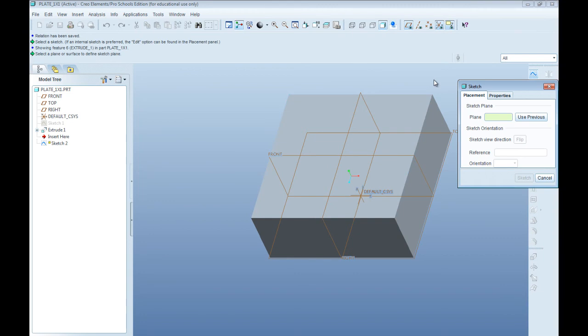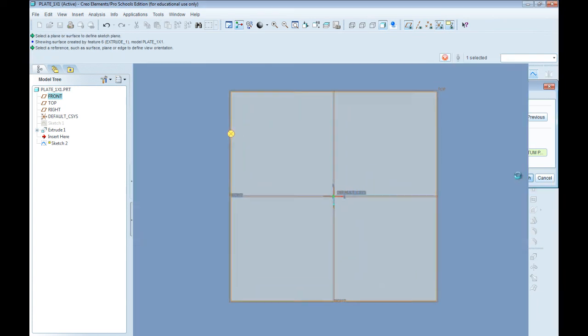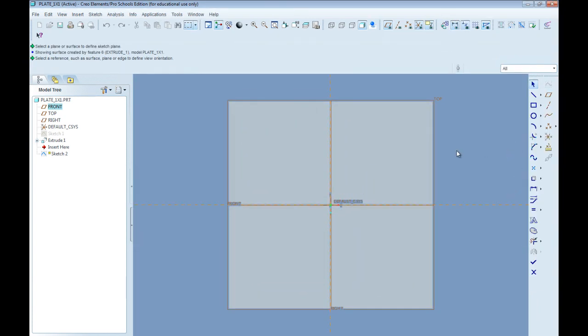So you see when we click sketch, we move over the top datum plane at the top of the brick. We can see that this is highlighted, meaning that we can sketch on it. So let's click, and then click sketch, so everything's set up. Now, when we create our drawing, we are drawing on the top of the brick, as opposed to drawing on one of the datum planes as we did before. So we create a circle, our peg here, or our stud.